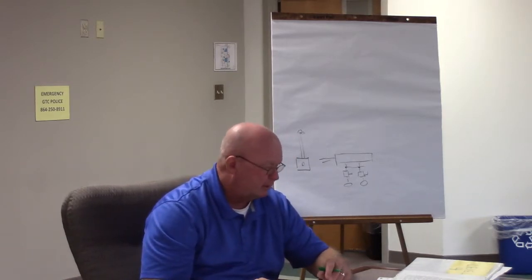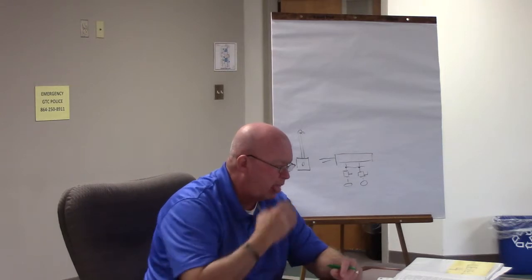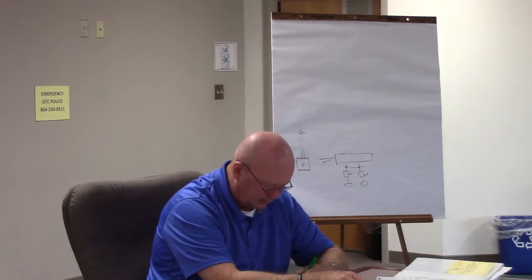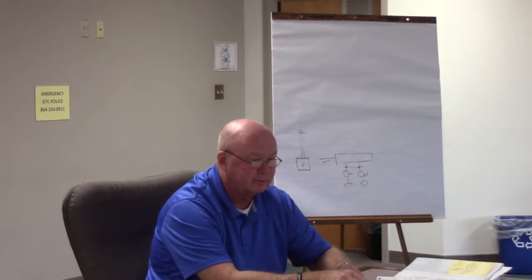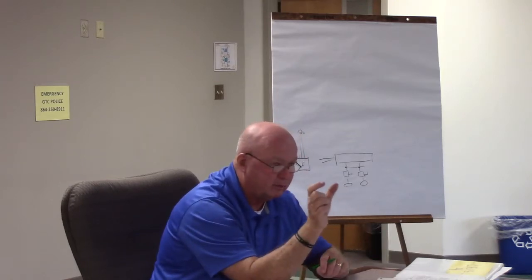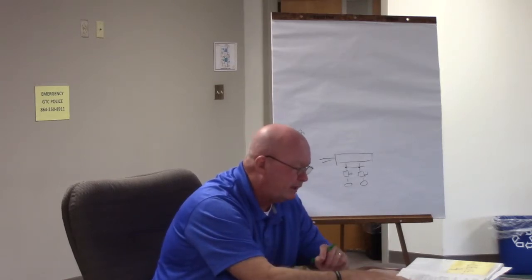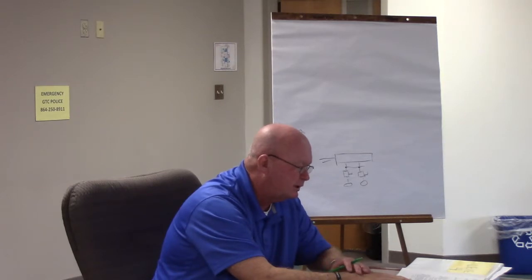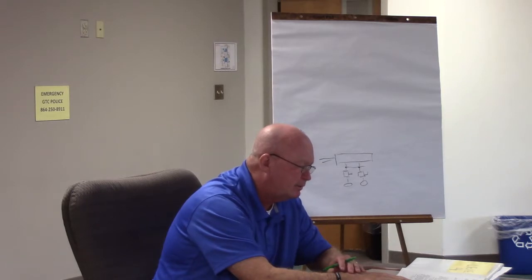Okay. Number 20. Transformer secondary conductors are considered taps. And we found that on page 8 and the little bullet point there. And that's found, it says section 240.21(C). Matter of fact, if you read that, it says transformer secondary conductors are considered taps and limited in length to not more than 10 foot, 25 foot, depending on the application and located inside the building.